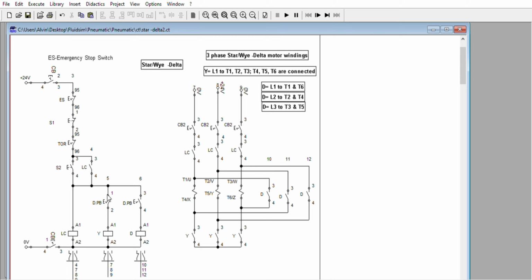This is a combination of normally close and normally open. They are in one package, wherein when you press the push button, this will open first and this will close, leaving this one open and turning this one on. So we meet that condition to open this one first and turn this on. That is by semi-automatic transition.